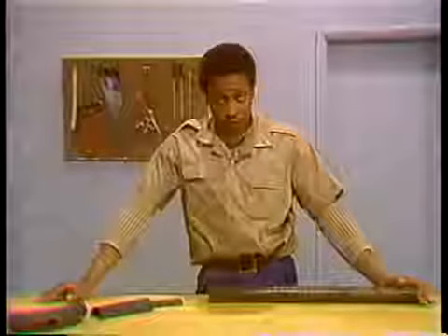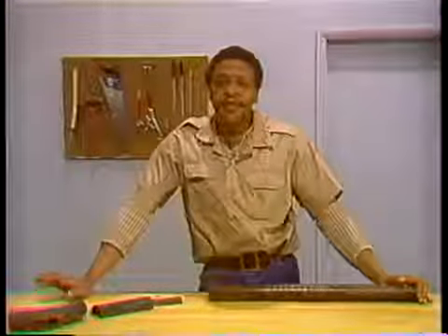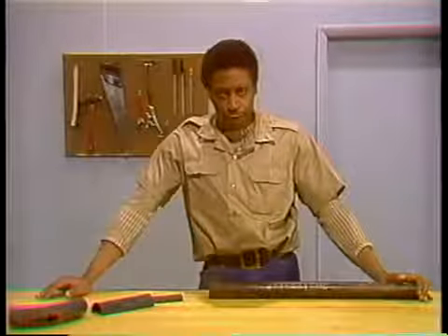Generally, we will cover how these repairs are made so that you'll understand what has to be done to repair a boiler tube. But first, let's discuss why tubes fail. There are 5 basic causes of boiler tube failure: overheating, corrosion, erosion, mechanical stress, and material defects. Each of these weaken the tubes and reduce their ability to contain pressure. Overheating is the most common cause of boiler tube failure.